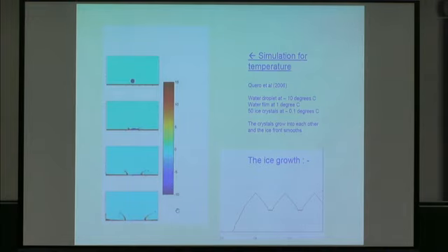So again, the droplet is coming in, and this is showing the temperature field, very similar to the flow field, as you might imagine. And this is for a water droplet at -10 degrees C. The water film was at +1, and there were 50 ice crystals spread along the surface here. Tiny crystals at -0.1 degrees. And the ice crystals were found to grow into each other and smooth out the bed. These sort of predictions can be used for aircraft usage.